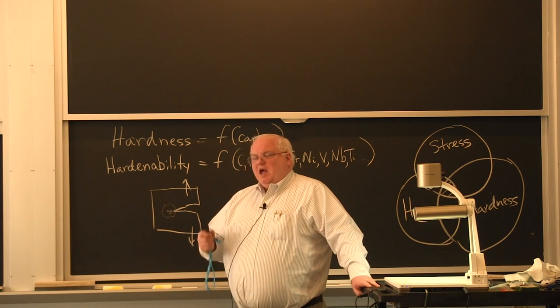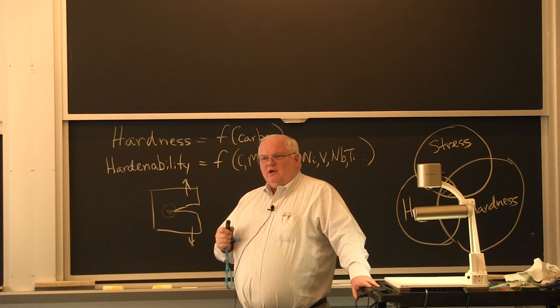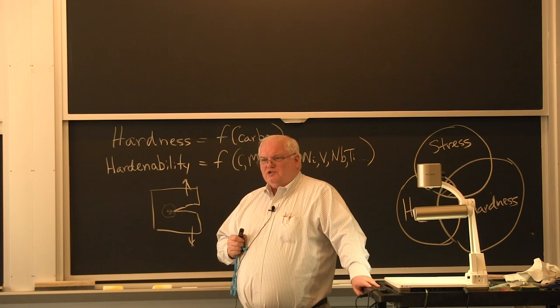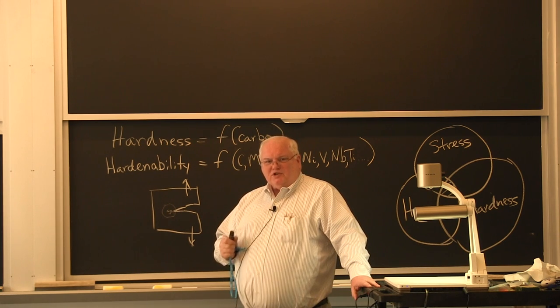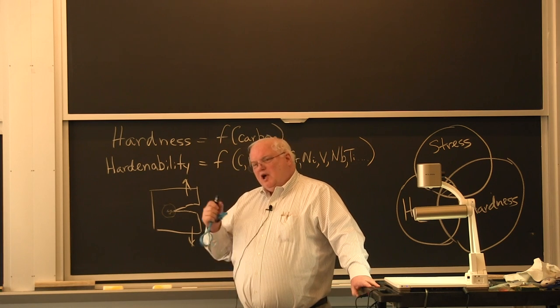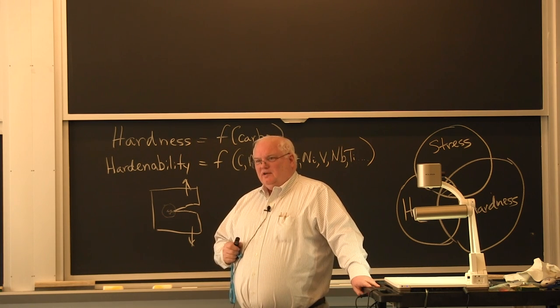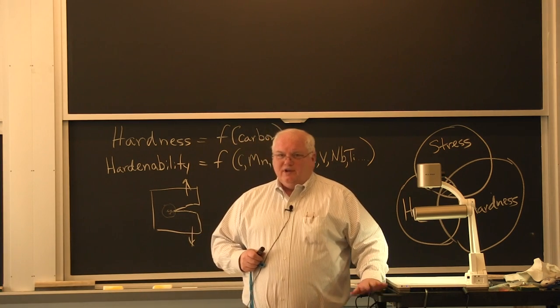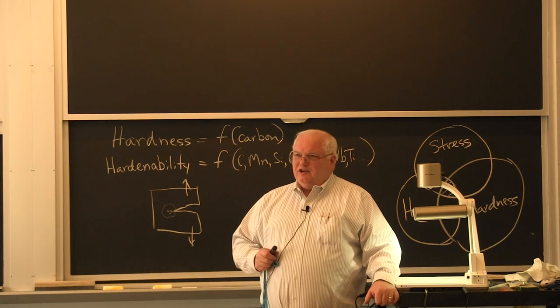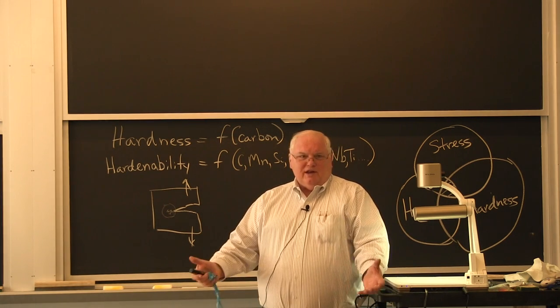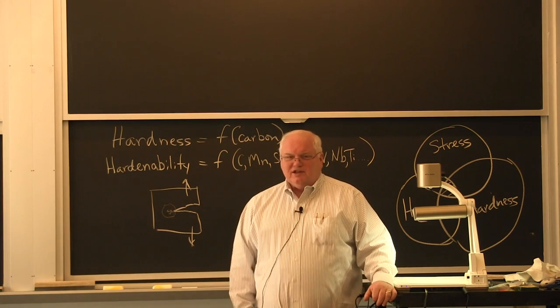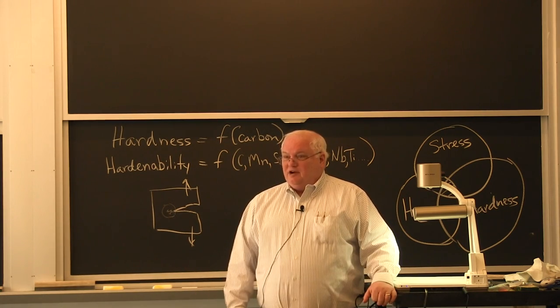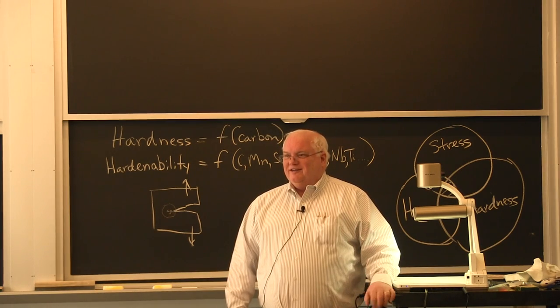So, moisture, humidity. According to the U.S. Navy, you're not supposed to weld a nuclear submarine if it's more than 85% relative humidity. Do you know how many days in a shipyard right next to the ocean on the east coast of the United States, which is where we build submarines, either in Newport News or in Groton, Connecticut, it's above 85% relative humidity? About 200 days of the year, it's above 85% relative humidity down there next to the water. It's not too surprising. So do they quit welding for 200 days a year? No. They keep welding.